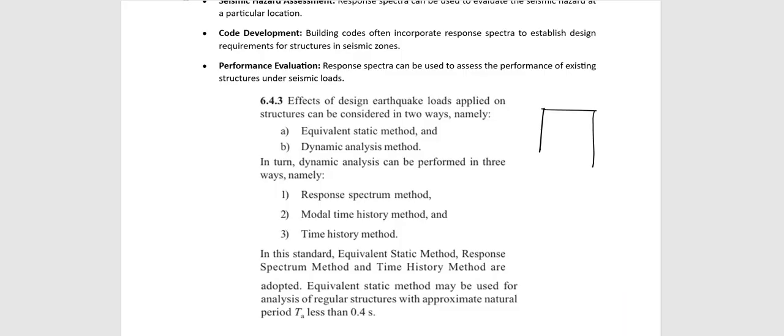What we have been doing is that we will be assuming that the whole mass of the system is assumed to be at this floor, like let the mass be m1. If it is having another story, then also we will be taking it as this is m1, this is m2, like that. Then we will be analyzing it separately. We will be analyzing with the mass m1. We will be finding a time period t1. Then for m2 will be another time period.